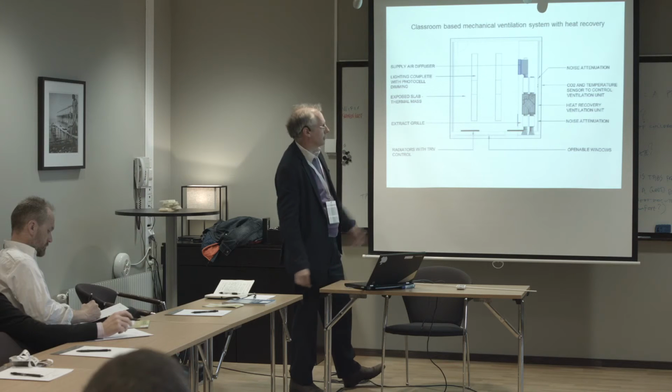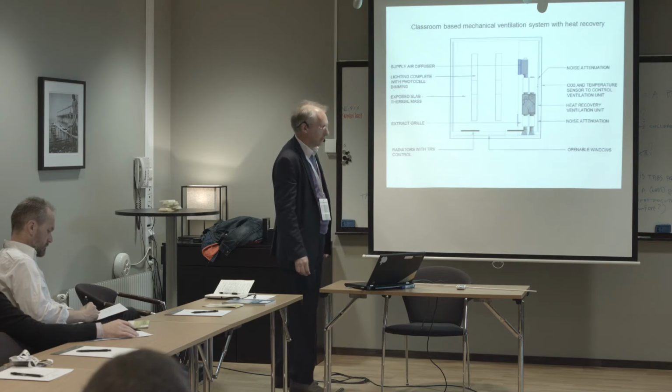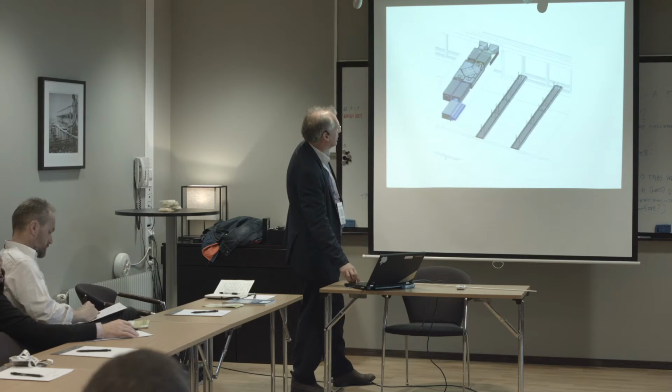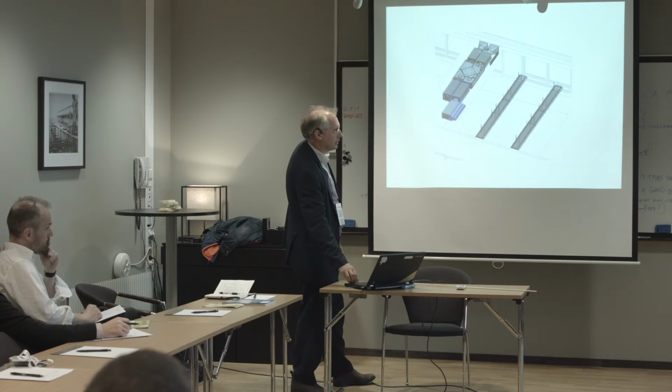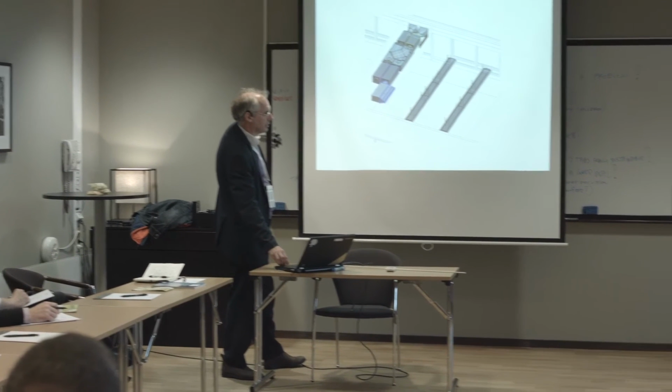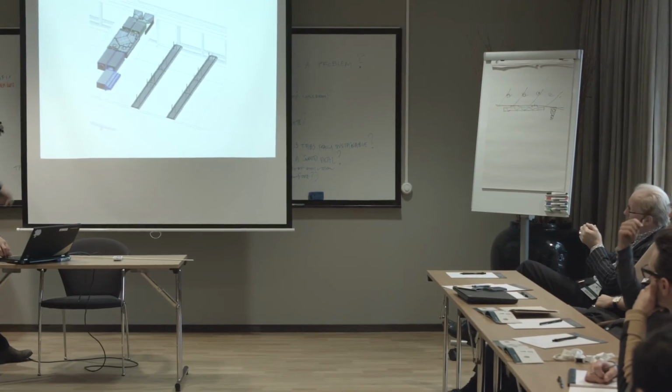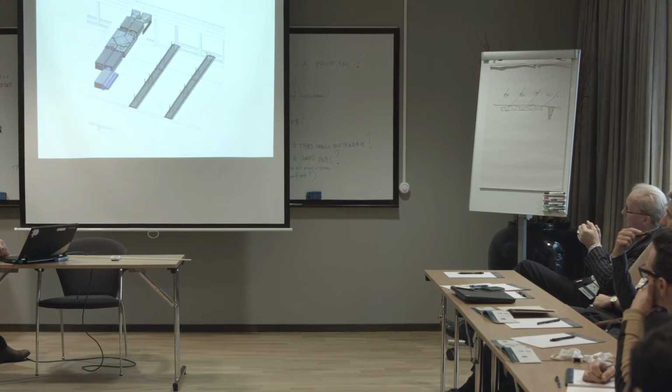This is the more conventional approach with a heat recovery unit. More maintenance. Just natural ventilation from outside, bringing it in without heat recovery. That's also allowed within the energy regulation. It will actually be more energy efficient over the year because this one has got more fan power.